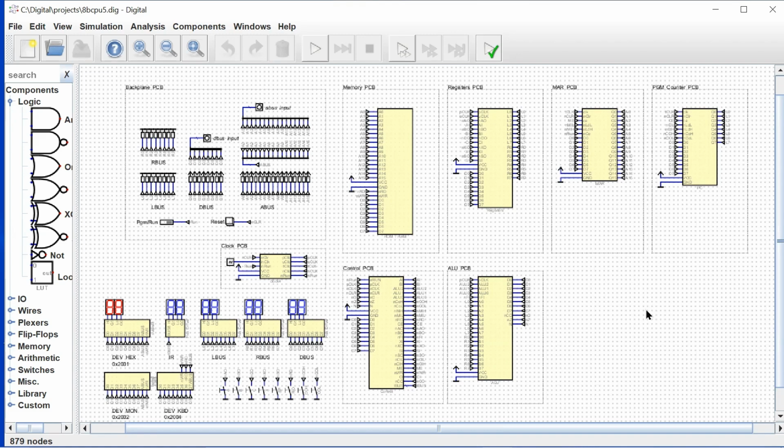First off, anything that remained of logical design where we were still using gates in our design, those have all been converted over to 7400 series ICs, and we'll see that when we look briefly at some of the designs. I also added input and output buffers to all the cards, and this was also suggested by one of the viewers back when we were designing the control unit.